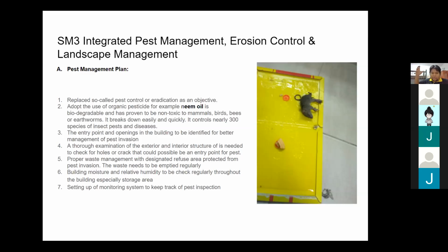So when you do construction on a hill like that, definitely you need to have some retention pond. So you need to talk to them, whether or not they did do a retention pond somewhere and how it was done. There's one at the back of the car park. If that is the only one, then okay lah. Otherwise, I think you need to get verification from the architect or from the contractor, with regard to retention ponds.